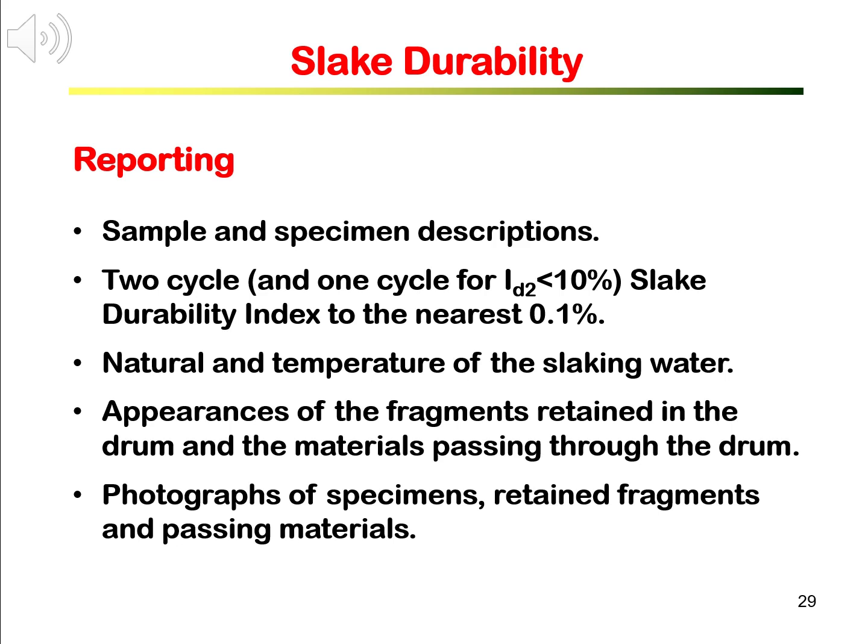Information on testing, including information on slaking water, source, and the temperature, for example, tap water of 20 degrees C. Any abnormal performance of the durability apparatus should also be reported, such as vibration, inconsistency in rotation speed.